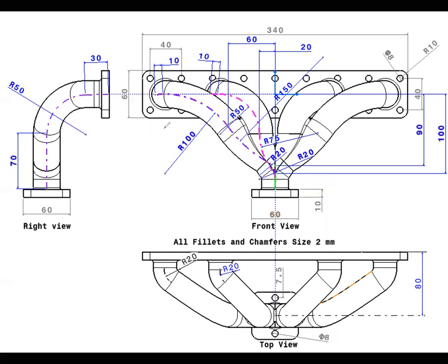First make the 3D curve of this one, from here to here. When we make the 3D curve, it only creates from here to here, and for the remaining we have to use another option, the 3D corner and line. Anyway, let's start making. Let's consider this is pipe 1 and pipe 2. First make the curve for pipe 1. The curve for pipe 1 is this one.